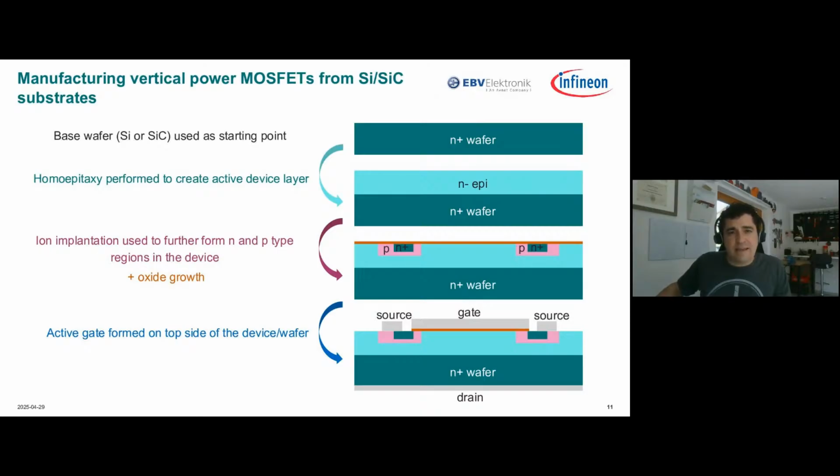The other thing is that if we're talking about a silicon power MOSFET here, this is silicon from end to end. Everything other than the metal is silicon. We have N+, N-, P-type silicon. We have silicon oxide. These are all homogeneous. Silicon carbide would be the same. Everything on here is silicon carbide. So if we wanted to make a GaN MOSFET, we would need a GaN wafer.